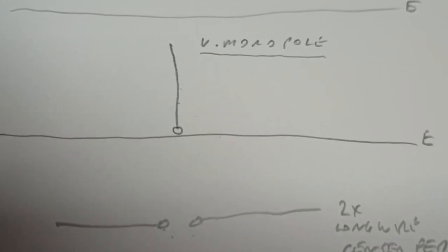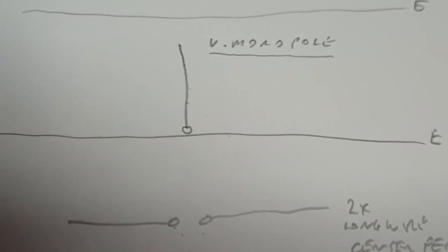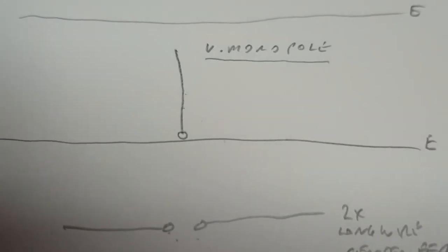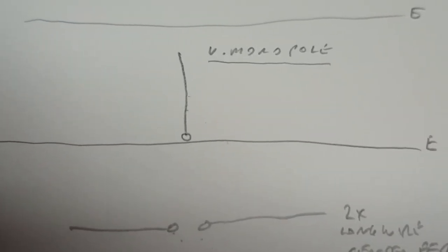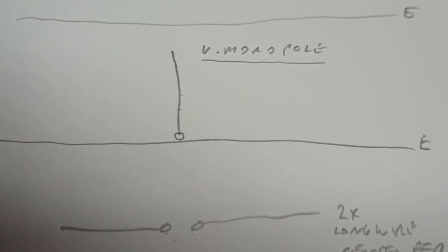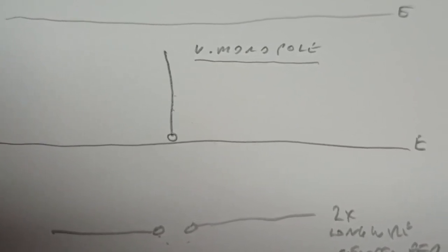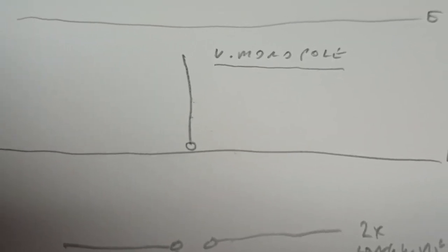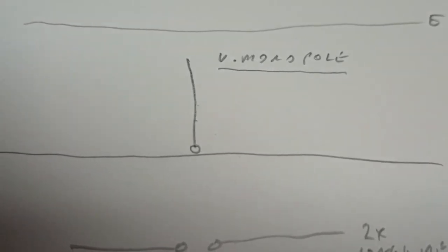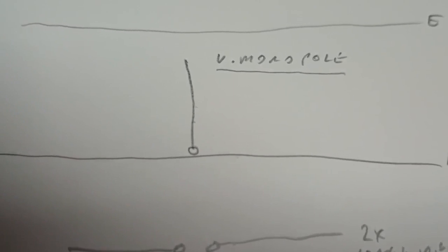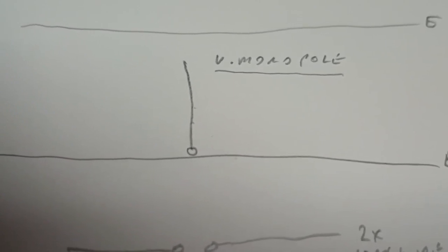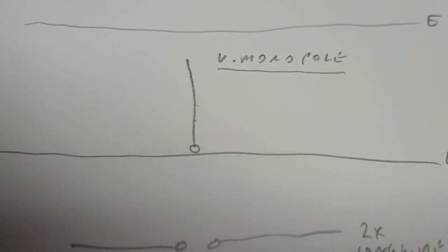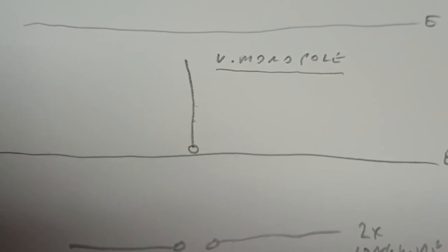It is wrong to say my antenna has ground radials. Wrong. Because the process of installing it and foolishly putting a bunch of copper wire in the ground to waste energy is part of the installation process does not mean that's how it works. What we've accomplished by grounding the shield is now we have field line coupling between the very bottom of that antenna conductor and the surface of the earth.